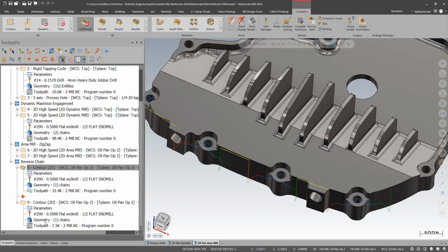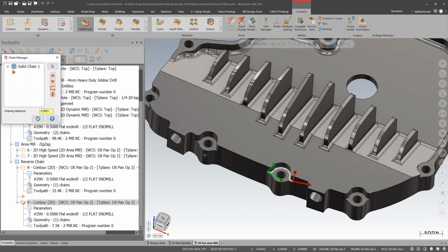And here I just have the other example. This one is wrong, but it's a single chain. And it would be the same thing if I used the right clicks. I'd have to reverse it. So double click the long arrow, but then it changes the comp direction, comp left, comp right. So I'd have to right click again and say change side, but I can also double click on the short arrow. So I can just double click on the arrows now.